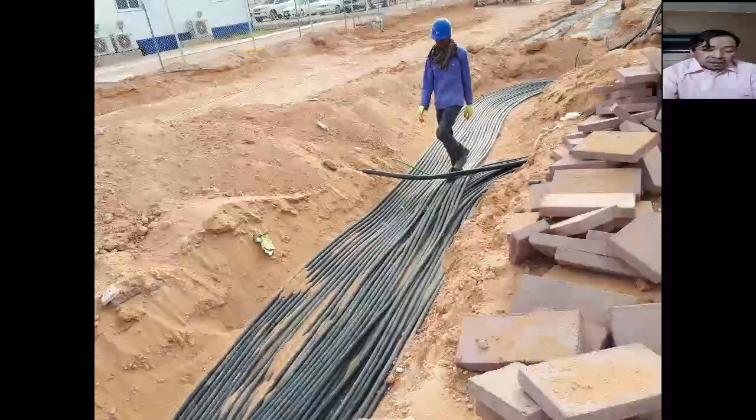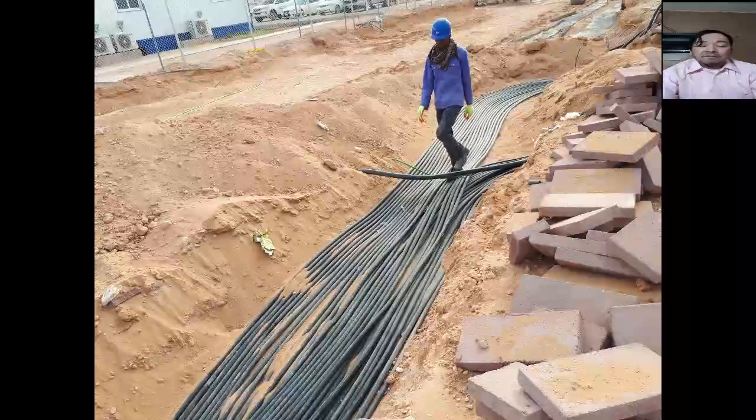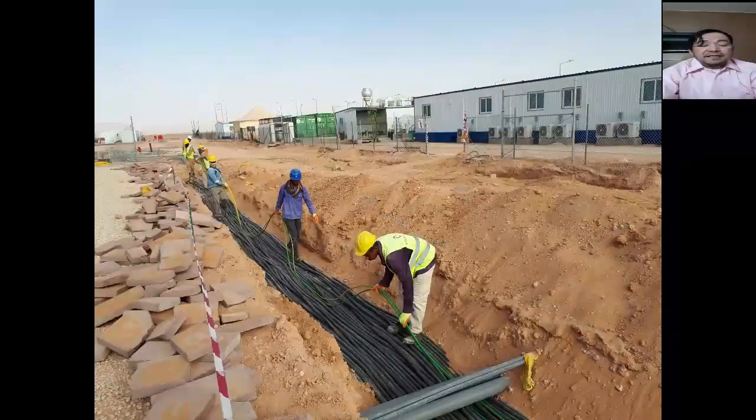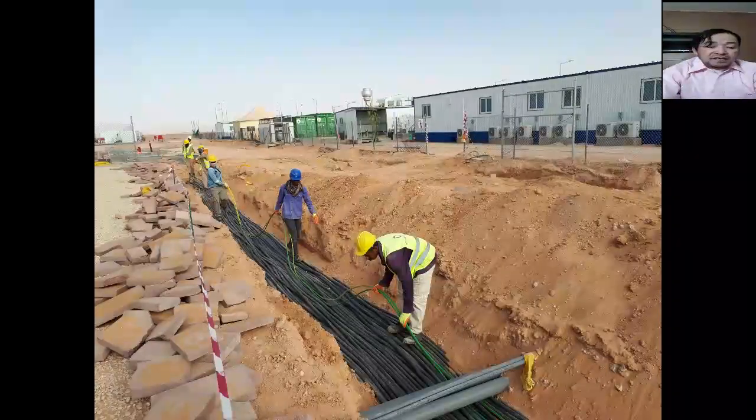Or C, a reinforced concrete encased duct bank with 150 millimeters of total cover measured from the top of the upper conduit, which shall include a minimum of 100 millimeters of concrete over the upper conduit. We also have another reference, the Saudi Aramco engineering standard drawing, which is AD-036874.